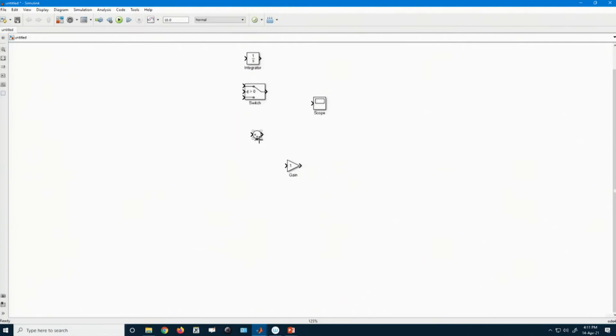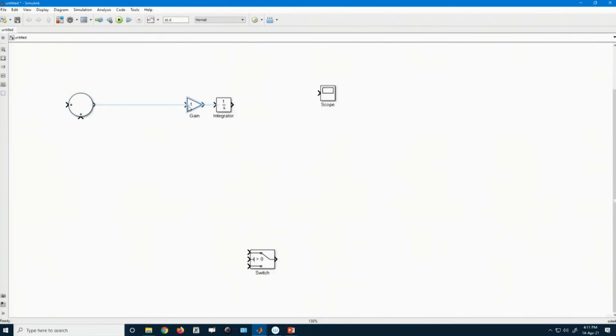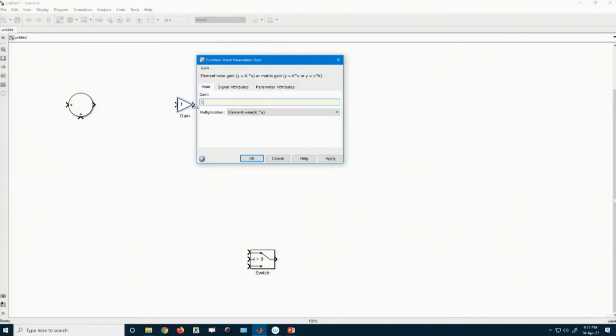Okay. So, let us start our block diagram. We want to first create a VL block. What is VL? We know that L dIL/dt is equal to VL, so dIL/dt equals VL by L. So, here we should use 1 by L. We already did this earlier.